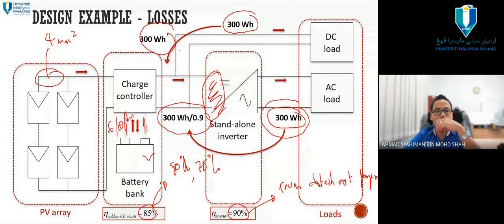But the battery cable, those who have worked with it may know, is 6 or 10, not 4. By considering we use the 10, and the charge controller is also MPPT, and you buy one that looks like a trustworthy brand, still we consider 85% as the safer side.